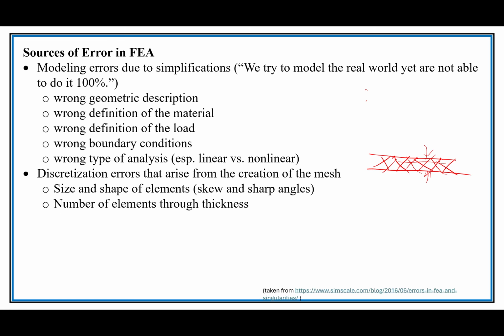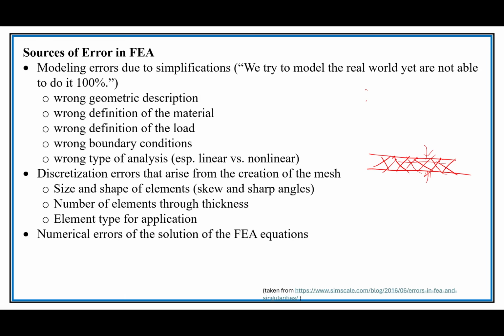And that's very true for things that are like plates. And that's why you want to have a plate element as one of your choices. It could do a better job of modeling the behavior of a very thin thing than taking a bunch of solid elements and trying to squeeze them into the thickness. And also the element types, you need to look up and understand them a little bit better, and not just pick them randomly from this element.